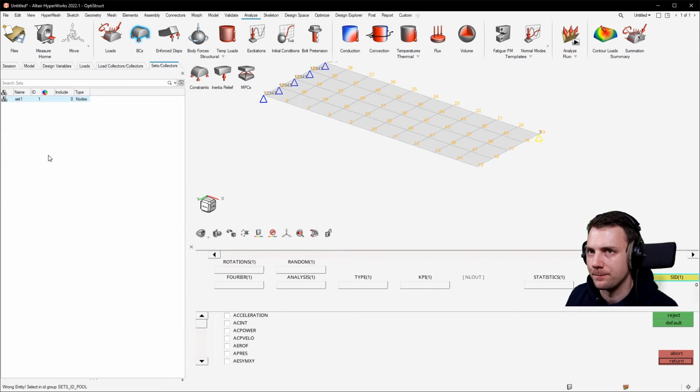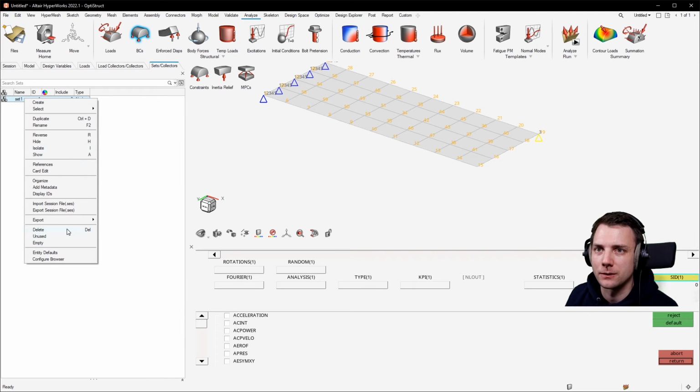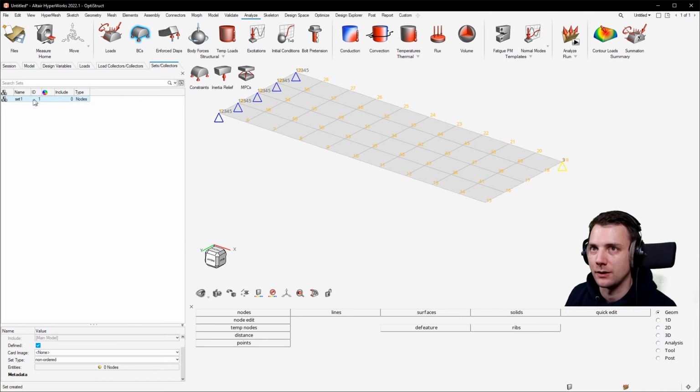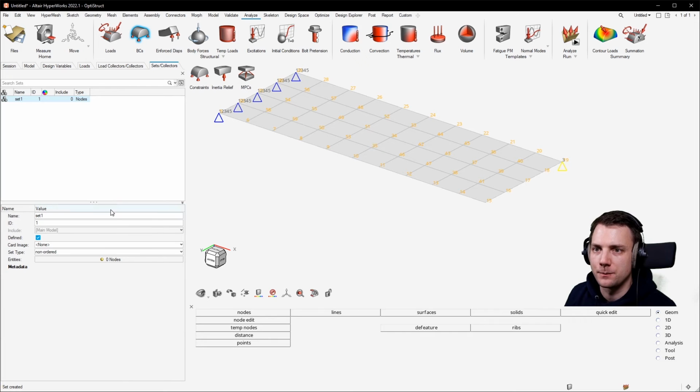Something is wrong here. Okay, now let's recreate the set. I'm not sure why it did not work, but let's delete the set. Let's create the set. Set 1. Now I'll just be sure that I am 100% safe about this. So we should go with a name, ID. All right, defined is also good. Card image should be none. Set type should be non-ordered. That's also correct. For entity IDs, select the 3 nodes. So this would be those 3 nodes. Hit apply. This is it.